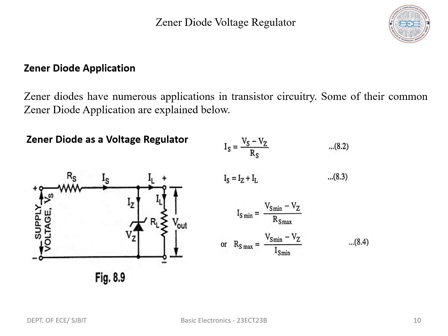Next, application: Zener diode as a voltage regulator. An important application of a Zener diode is its use as a voltage regulator. It is also called a shunt regulator. In the above figure, a current limiting resistor Rs is included in series with the source voltage Vi and the Zener diode to limit the current through the diode to a safe value.